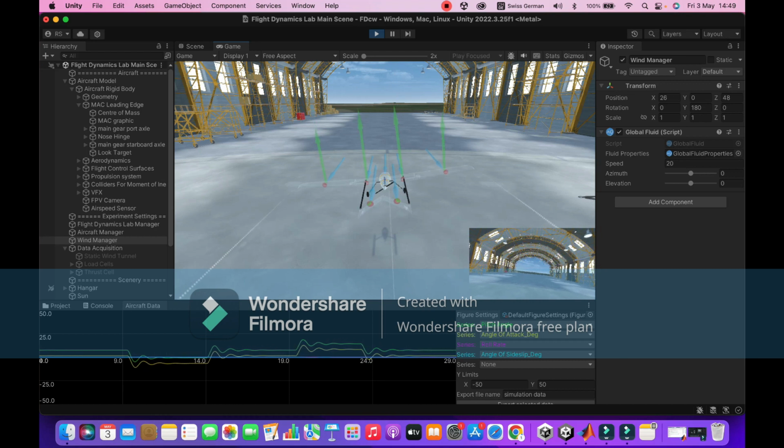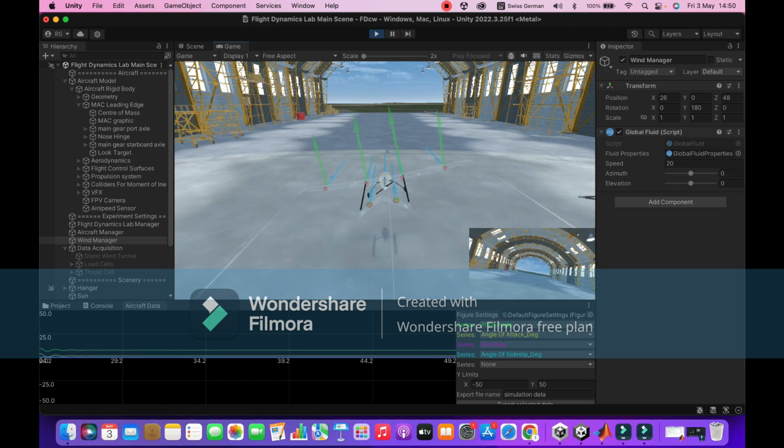The short period frequency is estimated by changing the free stream velocity between the stall velocity and maximum velocity at different locations of center of mass, and by taking the period of each cycle of oscillation and dividing 2 pi by it, the value obtained is around 7.5 radians per second, which is almost half of the predicted value. This could be due to aerodynamic nonlinearities, since theoretical models often assume linear aerodynamic characteristics for simplicity. And the damping ratio is found to be around 0.62, which is close to the predicted value.